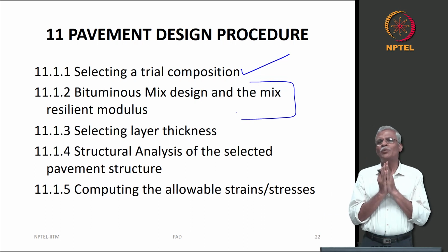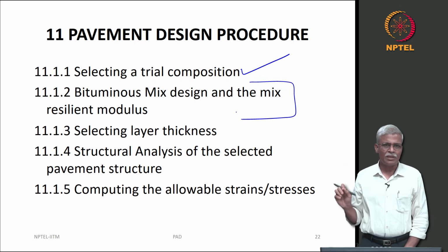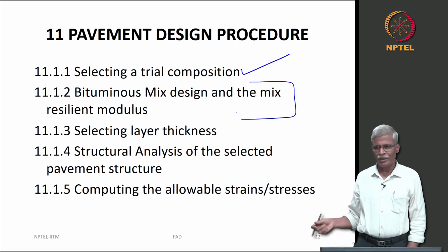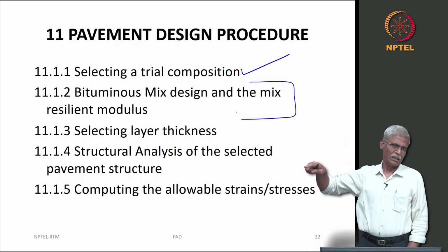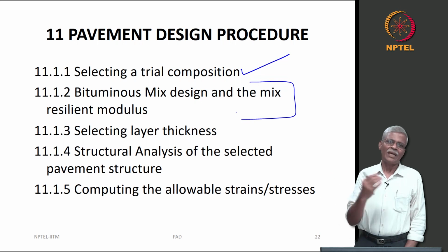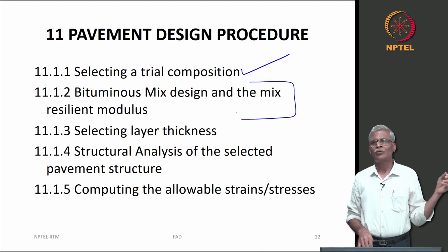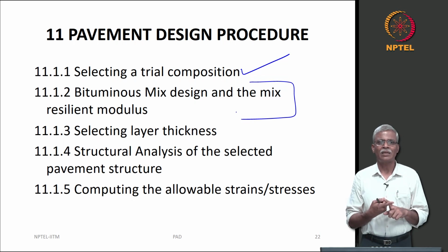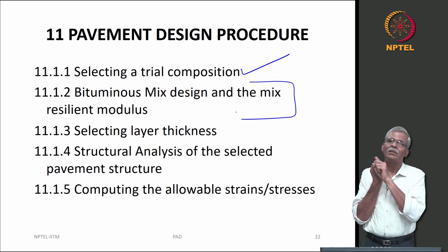Now, this needs to be emphasized very carefully. If you are doing a concrete slab design or concrete beam design, you assume an M20 or M30 concrete, and the construction site knows very clearly how to make that M20, M30 concrete. There are procedures systematically followed. IS 456 will tell you, if you know the grade of the concrete, what the modulus values and flexural stress properties are that you need to use; they are also given very clearly. So the mix design and the structural design, the modulus value used in the structural design, are intricately connected. That is not the case here.